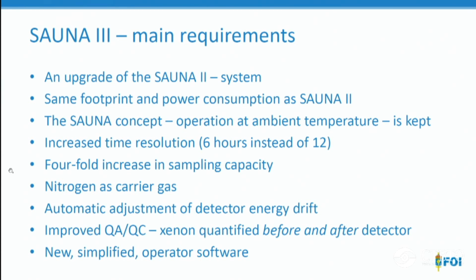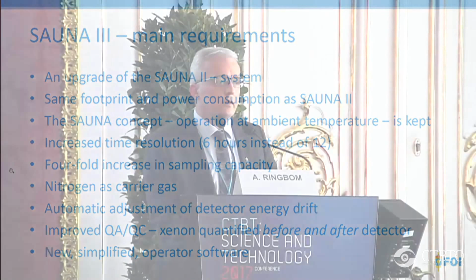We will go from helium to nitrogen as a carrier gas, and develop an automatic adjustment of the detector energy drift. Another thing we have done is to introduce a stable xenon measurement before and after the cell as an extra QA/QC control. And then finally, simplify the operator software as well.